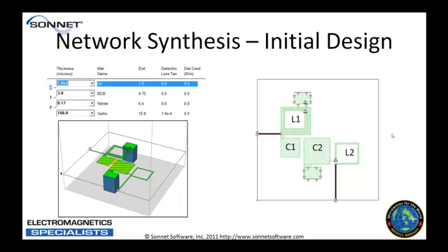You can see a 3D view here at the bottom, the planar view over at right, and the stack up of the materials pictured here at the top. We're going to use 100 microns of gallium arsenide. Then between the plates of our MIM capacitor, we have 0.17 micron thickness nitride material. And then there's a passivation layer of about 3 microns of BCB material over the top.